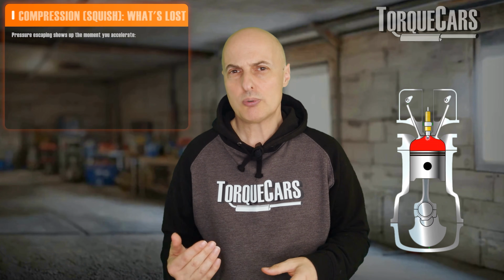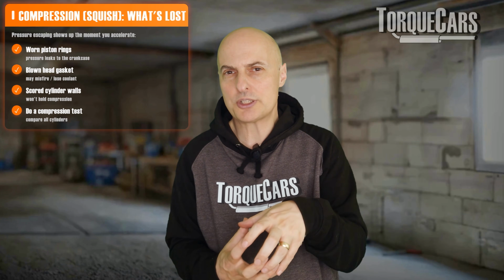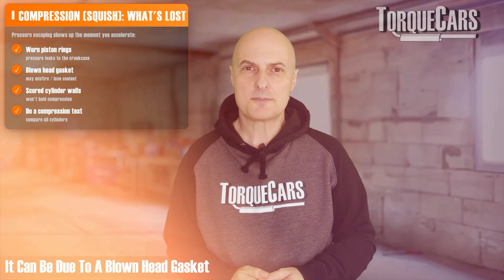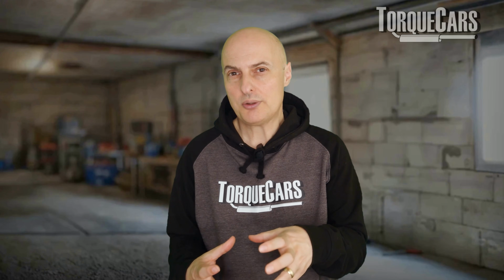Now, what can go wrong on a compression stroke? Well, if the rings have become degraded, the compression is lost in the engine. It's not able to compress the air. Some of that pressure is being lost into the crankcase. It could be a blown head gasket or even scored cylinder walls. They can all lead to this loss of pressure on the intake stroke. When you're under boost, you need all the compression you can get.